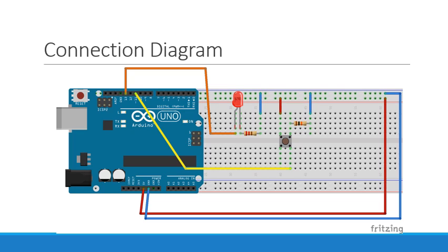You can see that one end of our button is connected to a resistor which connects it to ground. This is to bring down the value of the button to ground anytime it is not pressed. Then the other end, which is also connected straight like this, is connected to the yellow wire, which is our digital pin 11. Then the LED is connected normally. The other end of our button is connected to 5 volts, as we can see.